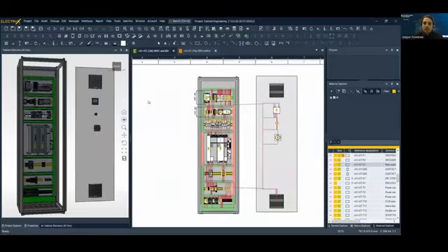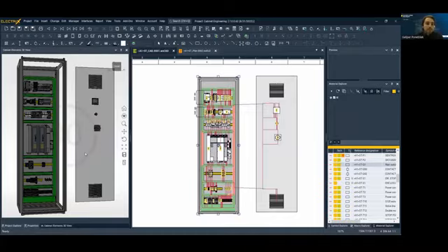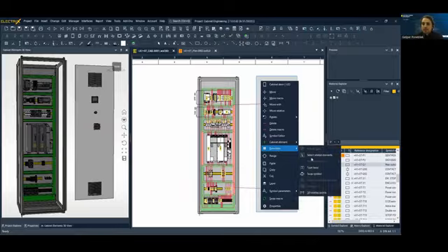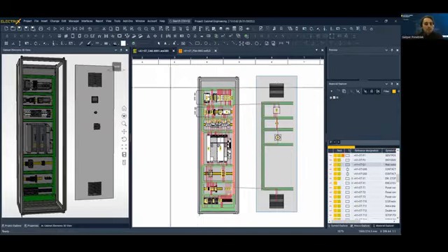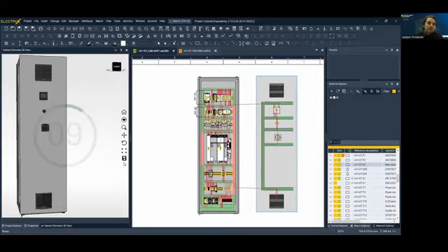So we can now insert this side door, side wall, and check it again in our 3D model. And we also have the collision check. If we close this door, the collision check will warn us if a part is not placed right.